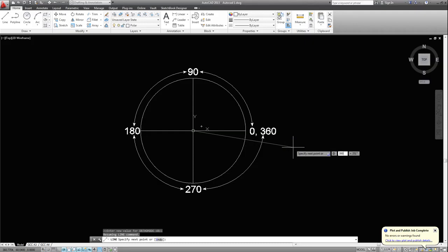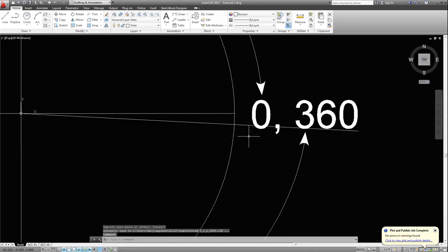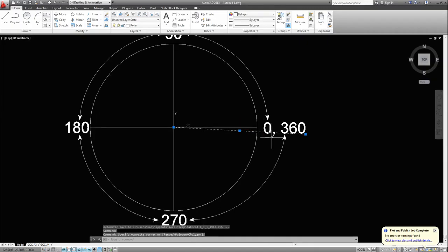Now you see in the next it's actually got the correct degrees in there for that quadrant, and it's got the greater than symbol, so a shift greater than, because you've got to press the shift key on the computer keyboard to access that tool. And I'm going to type, what did we say, it was 357. If it was 3 degrees below 360, I've typed 357. Press enter. Remember I said enter and spacebar are exactly the same in AutoCAD. That line there is now at 357 degrees.